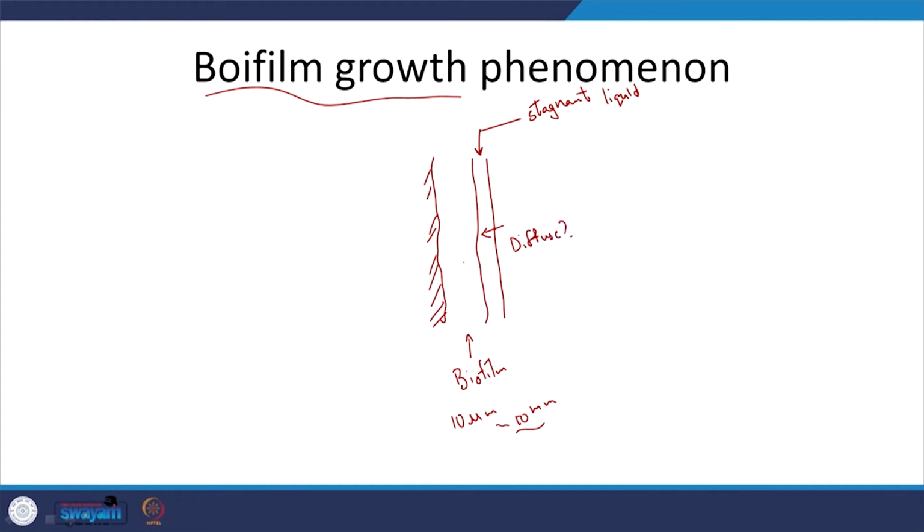So, this is where the degradation takes place within the relevant biofilm, but what has to be degraded? Your organic matter has to degrade, and it needs nutrients and oxygen, right. These need to diffuse through this stagnant liquid film here, and here you will have the bulk liquid, the water that is flowing or trickling over this layer. This is your bulk liquid, and here you have your oxygen or the air. So, that is how the biofilm looks from the side view, if I may say so.